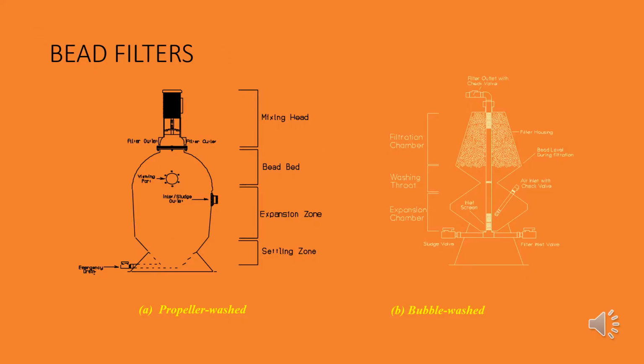Generally, after you use a settling chamber to get rid of all of the solids that could be pulled out by gravity, you're probably going to have to use some other mechanical filtering device to remove the solids that might be suspended. Anything that we use in our lab or on most of the farms in Florida would fall into one of these two categories of bead filters. In each case, you have small plastic beads that sit inside a giant canister.